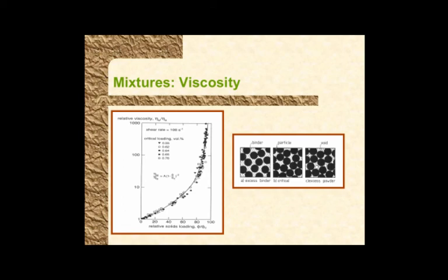And so on the one hand, to make the shape, you want as low a viscosity as possible. On the other hand, after you remove the polymer, you need sufficient strength, and you've got to operate in the space over here. See, small changes in volume fraction of powder result in large changes in viscosity. Right? So the room for error is very low.